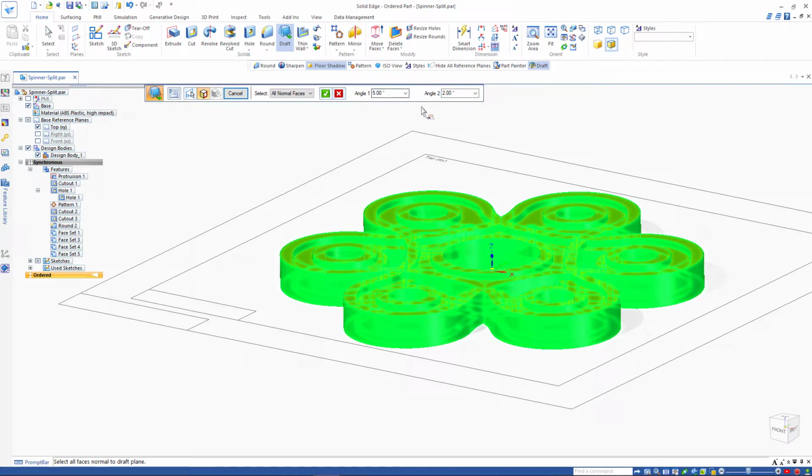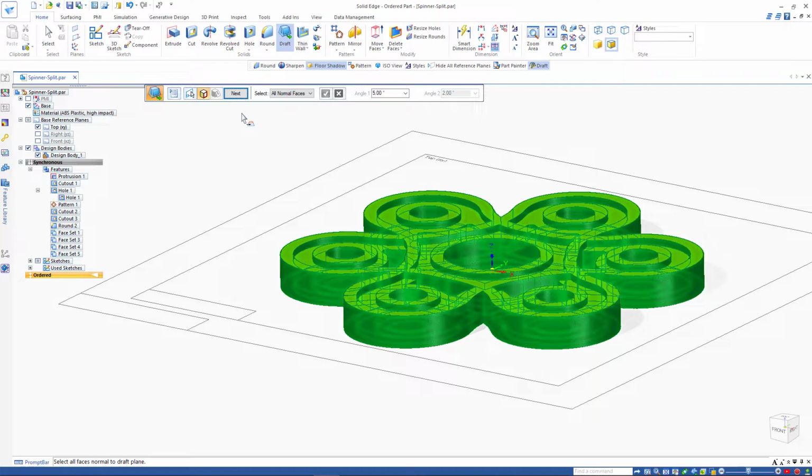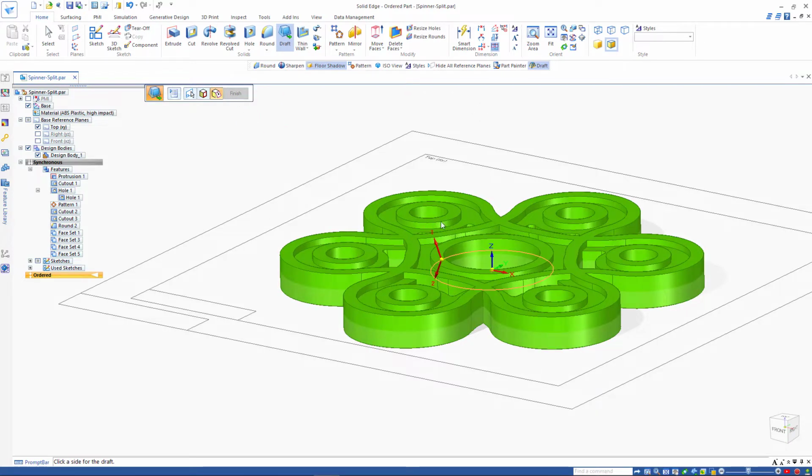And the reason that I would have a lesser angle, I would want the lesser angle on the ejection side of the mold. The lesser the angle, the more likely it is to stick to that side. And that's the side I want it to stick to, the ejection side. So I'm going to put less of a draft angle there compared to the top. I'm going to accept it. Next. So you see angle 1 is 5 degrees. Angle 2 is only going to be 2 degrees.